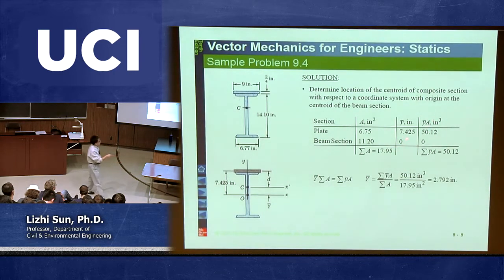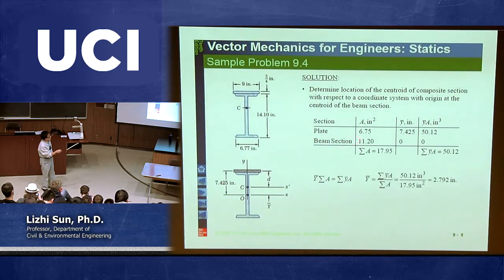Okay, going back to look at this picture. Keep in mind this second row, I'm talking about the local y bar, the lowercase y bar, with respect to the second geometry, this W14 by 38. For this one, we are picking x and y passing through the centroid, or the center point, of this second part.